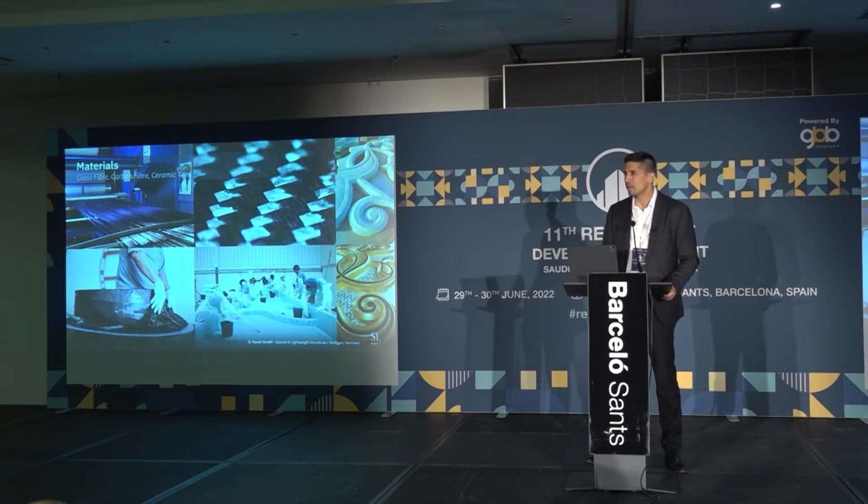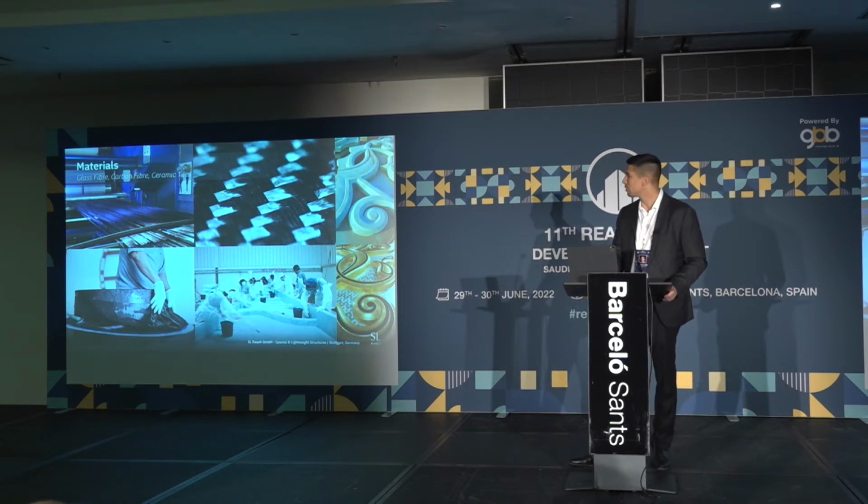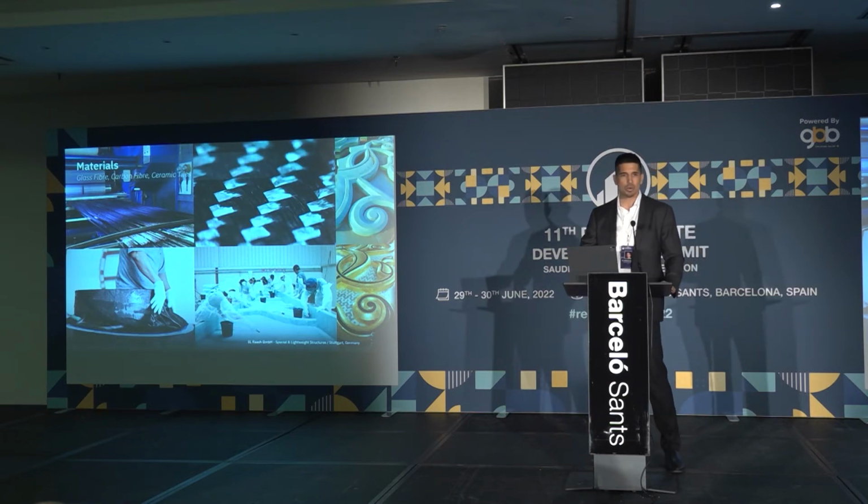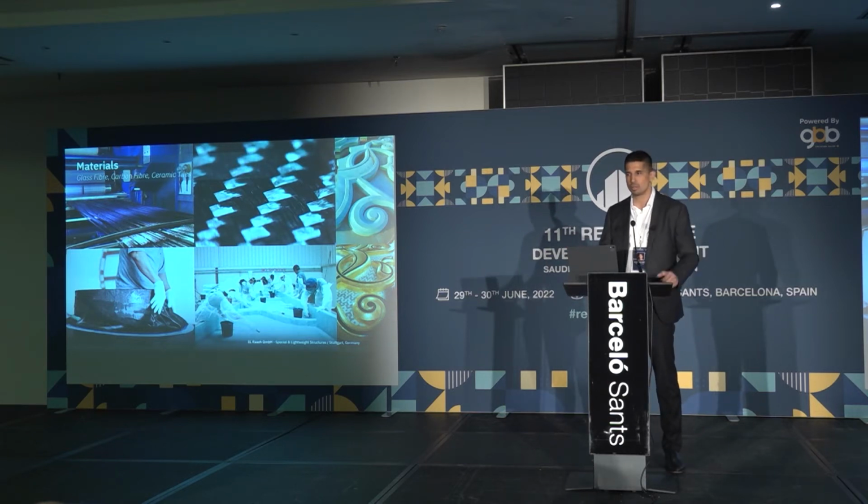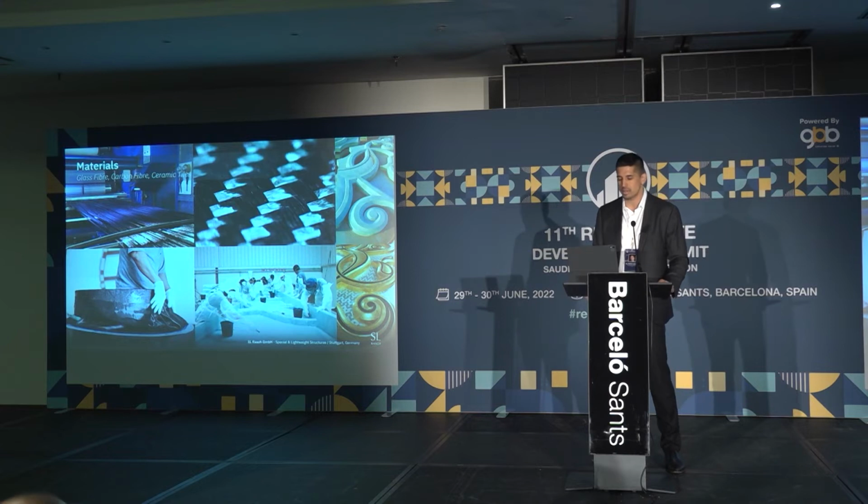Also today, one of the governing facts is the right materials. Here you can see the process of a carbon composite structure being put together. First, you have the carbon fibers, which are weaved together to large sheets, and then they're treated with resin and put into a mold. Within the mold, there is a foam core put inside, and then the whole composition is put in a big oven, an autoclave, in order to cure them and then transform these materials into an ultra-lightweight, high-strength, and very efficient